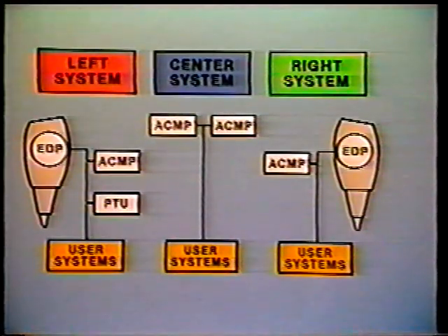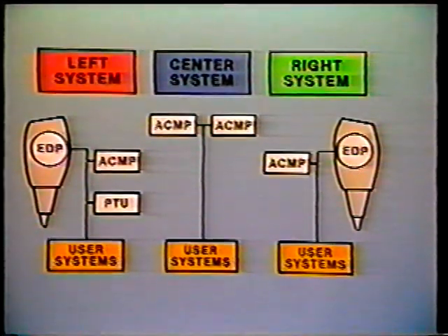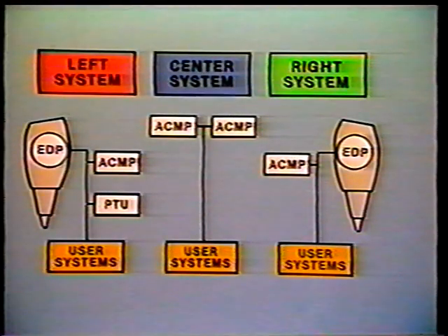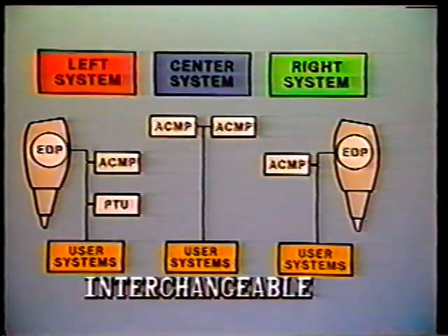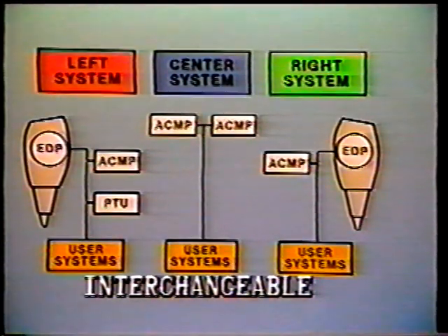The center hydraulic system is pressurized by two ACMPs, which normally operate full-time. The ACMPs are exactly the same as those used on the left and right systems and are interchangeable. The ACMPs are located on the left aft body fairing.